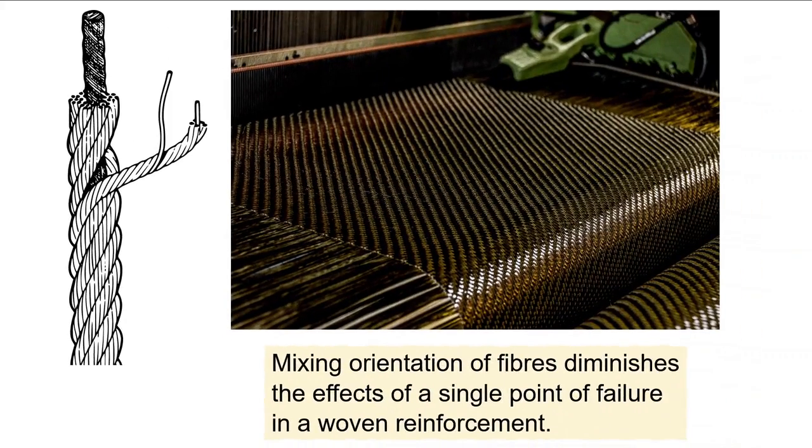Woven composites take advantage of this same type of approach. Textiles are like two-dimensional ropes. There are fibers which are woven together to form a cloth-like material, which then can be soaked in partially polymerized resin, also known as pre-impregnated or pre-preg for short, and then built up in varying orientations to form a final component. In the same way as your jumper won't fail immediately because there's a small hole in it, so too is the case for woven composites.